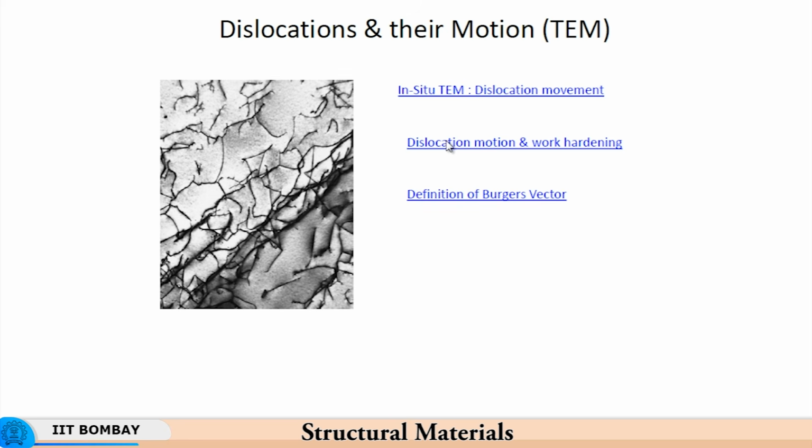So the body centered cubic iron lattice would have carbon atoms occupy the interstitial spaces, and these carbon atoms are the ones which will impede dislocation motion. And that is how we say that strength has been added by addition of carbon atoms. So the more carbon is added, the more the strength of the material, and that strength comes from these interstitials impeding the motion of the dislocations.